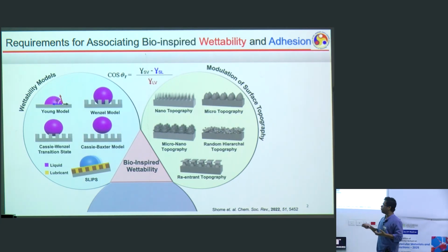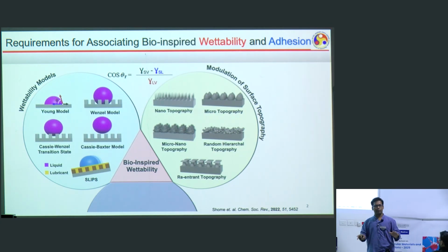Okay, balancing of the force acting on this droplet, and if you have a 2D projection, on the right hand side and the left hand side, two unique points. So basically, this red one is the surface tension, right? This is gamma LV and a cosine component, plus this gamma SL equals gamma SV, right? It's just the balancing of the force. It's not a magic formula.